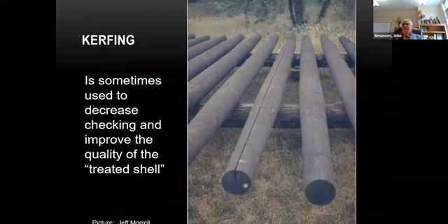So now if you treat it after you kerf it, you have created a shell of treatment, and that shell will protect the wood that is below it. So as long as you have the shell there, then you won't get decay. So that's another technique that's used.